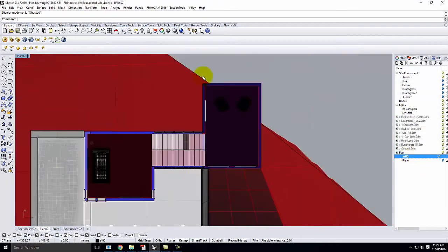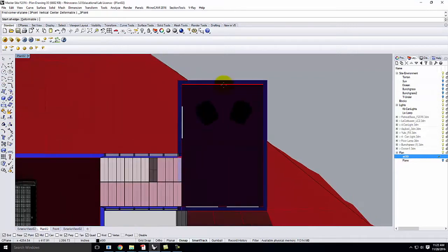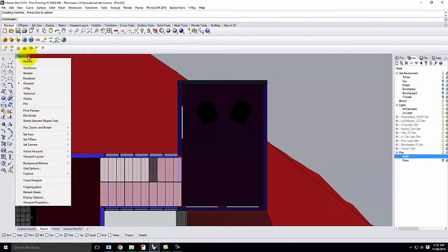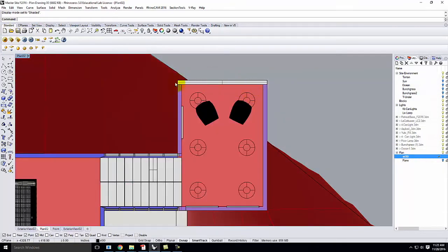So we'll be on the ST00 layer, and I'll use my planes to fill in with surfaces. Let me show this. This might help if I showed it in shaded mode so you can see it. There's the surface. I'm going to continue with my rectangular plane, I hope. And we'll work our way down this side.